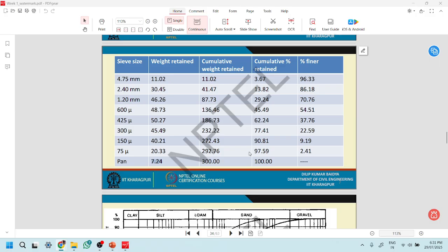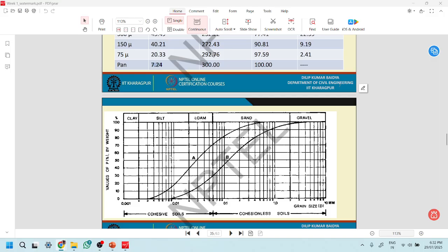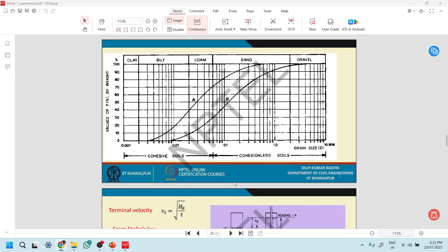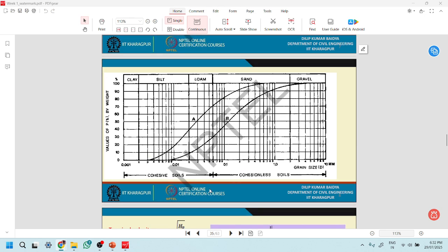So if the two materials are not reacting with each other, they are forming a third type of granular structure, you can definitely do the sieve analysis on that and use the same properties here. But then you have to discuss what is the change in the properties that took place with what you did. I hope that is clear.